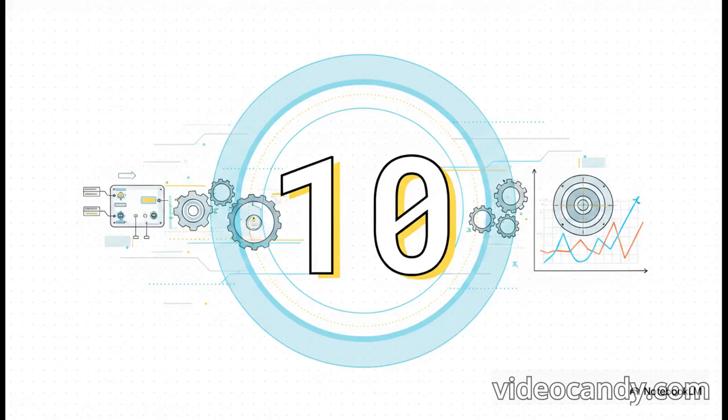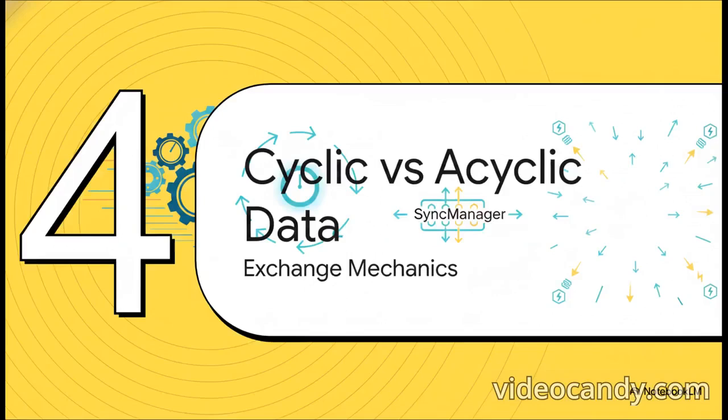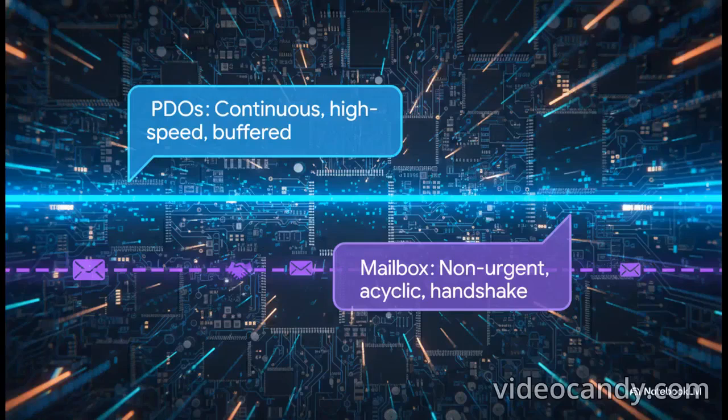This is a real game changer for motion controllers, because when you calculate velocity from sequentially measured positions, even a microscopic timing jitter creates massive velocity spikes. But with 10 nanosecond precision, your velocity calculations are absolutely flawless.